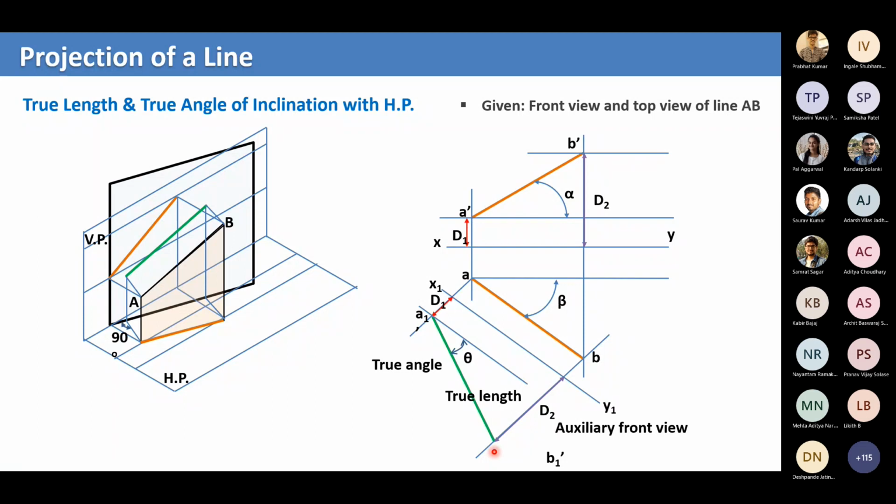Now this dimension is nothing but the dimension we take from the other view. Since this is the top view, the other will be the front view. This is the dimension D1, so this D1 is the same D1 here. When you draw the perpendicular and extend, you extend to D1 and mark that point as A1, because we are extending from A. Now you start from B, draw a perpendicular and extend it.